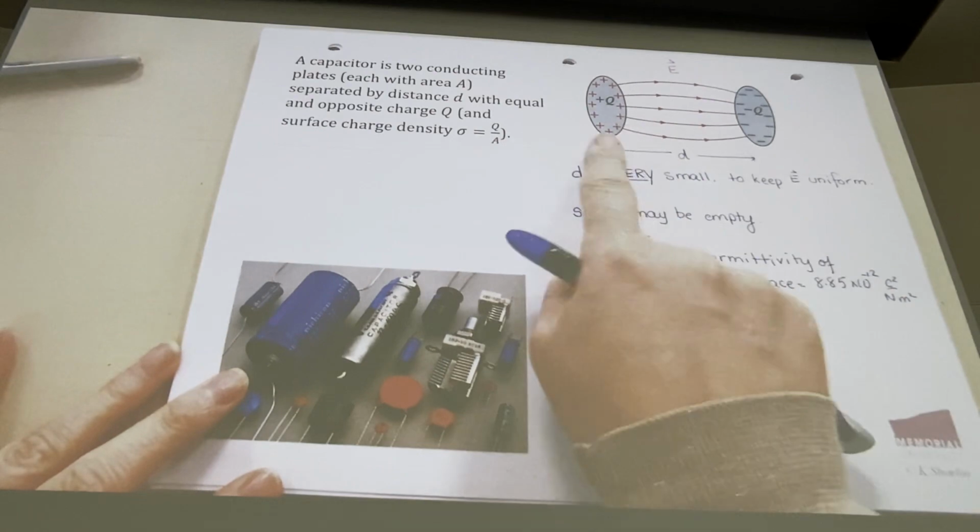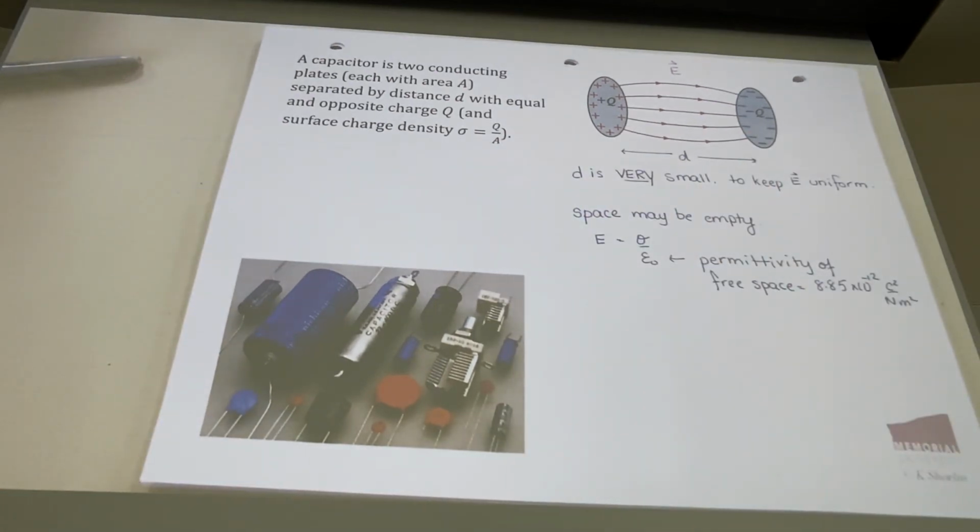Right off the bat, you might recognize a problem with actually trying to fabricate a capacitor. You have these two tiny plates and you want them close together. If the two plates touch, all of a sudden you've got a short circuit and you can't get that electric field because there's no distance between them anymore. That's a problem in your circuit, so you don't want the plates to touch. The way we make that happen is we put something between the plates, and that something is called a dielectric.